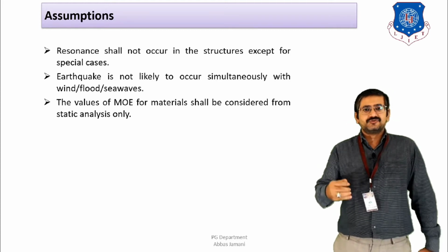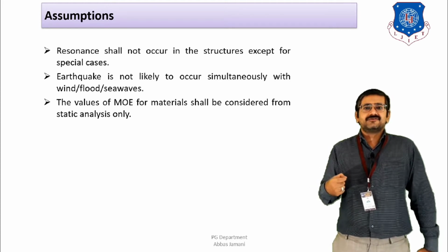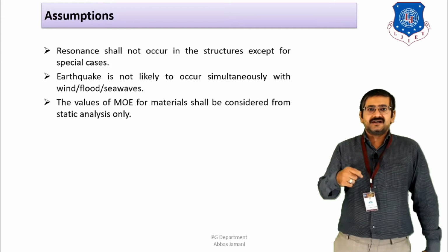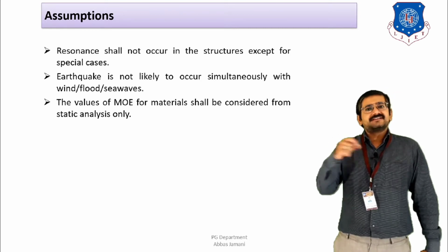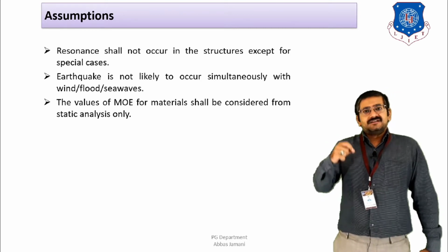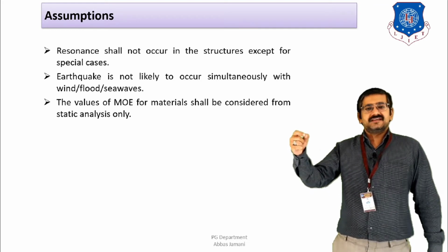Sometimes the intensity is more, sometimes the intensity is less, and depending upon the intensity and the magnitude, and also depending upon the location, the features of the earthquake such as focal depth, the load path, and the soil strata through which the waves are going to transfer, all these are going to affect the ground motion. And based on the ground motion, the ground acceleration is going to be transferred to the structure, and then the ground shaking is going to initiate in the structure itself.